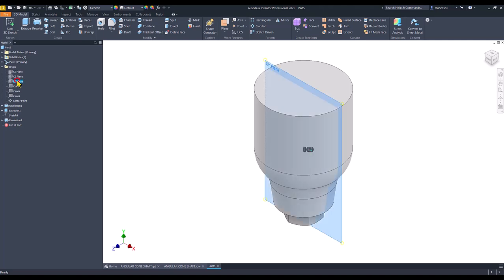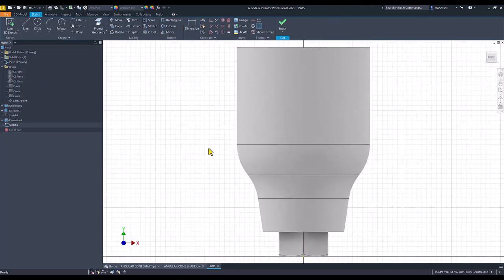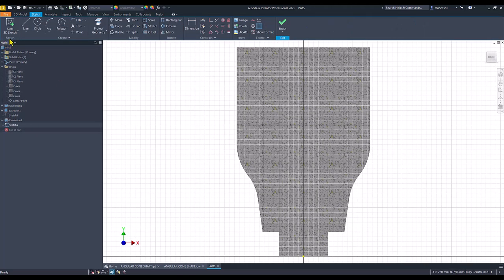I use the plane XY, F7, and I draw a line from this corner to this generator, but I have to project geometry here. Trim this end. And what is this dimension, my friends? Do you know? 40 minus 30, dimensions in the drawing.